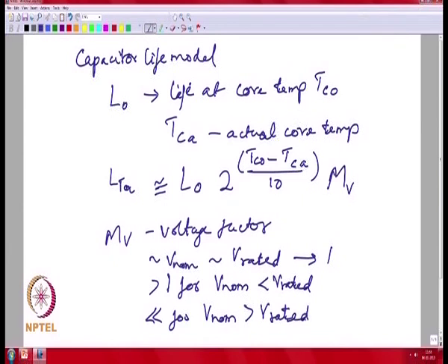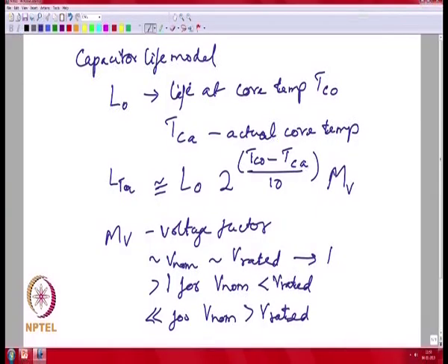Many times you can have a 400 volt electrolytic capacitor where, for a short duration, for a few seconds, you might be able to take it up by a few tens of volts above 400 volt, but if you hold it at that level for a long time, it will actually get damaged in a matter of seconds. But for a short duration you can take it above the rated voltage. It is not recommended for continuous operation or design.